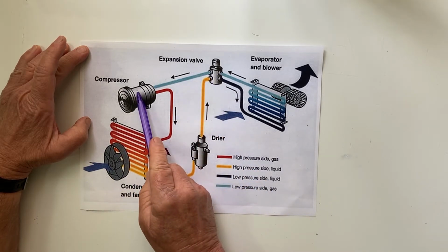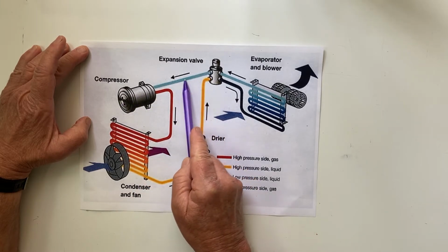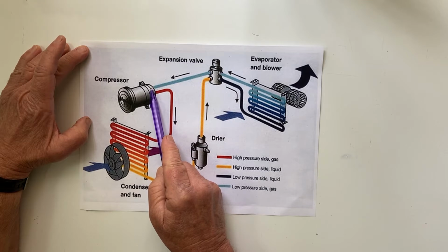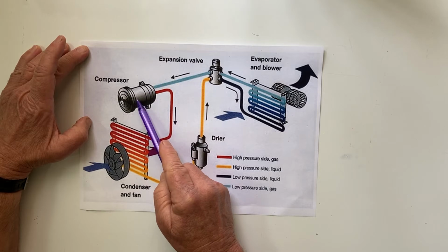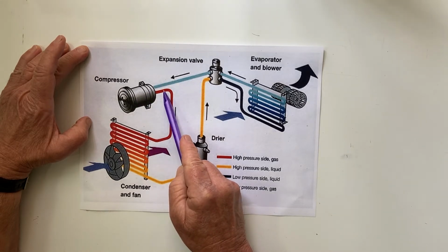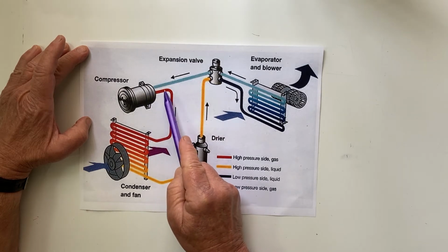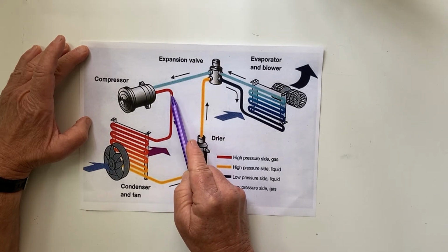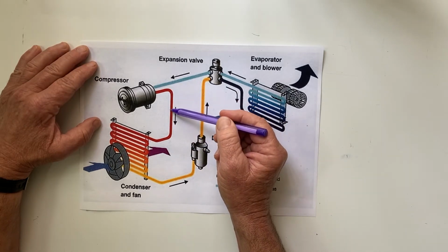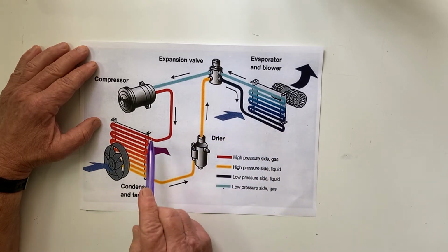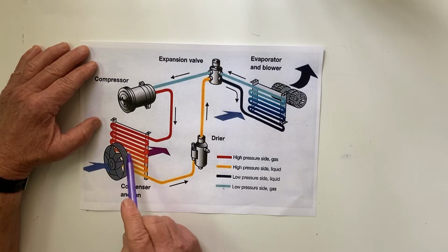So with the compressor clutch locked in and the compressor running, we're going to draw in a low pressure, low temperature gas. Now it's compressed from the low pressure into a much higher pressure, but it's still a gas. So it comes in as a gas and it goes out as a gas, but at a much higher pressure, and that in turn generates a huge amount of temperature. To remove that temperature, it then passes through the condenser, and as it makes its way down through the condenser, as the name suggests, it condenses.